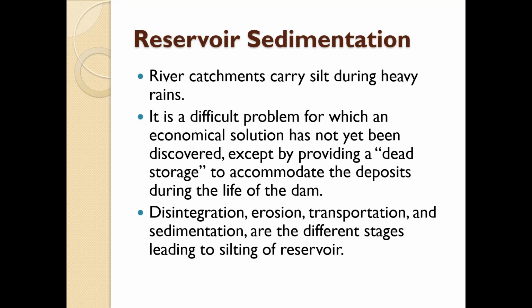Then it is evident that the dead storage will be filled up in 40 years, and the total storage in about 200 years. Hence, the usefulness of the reservoir would start reducing after 40 years, and after 200 years it would be nothing but a collection of sand and sediments with no water in it, provided the siltation rate remains constant at 0.15 million cubic meters per year.